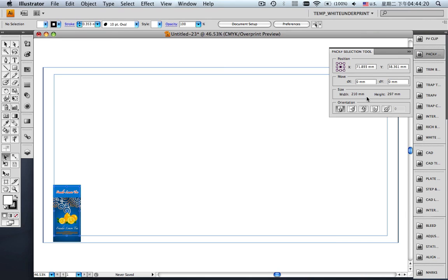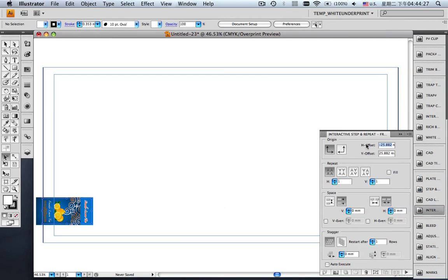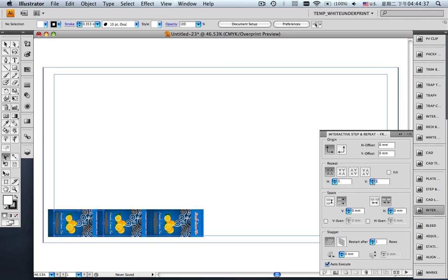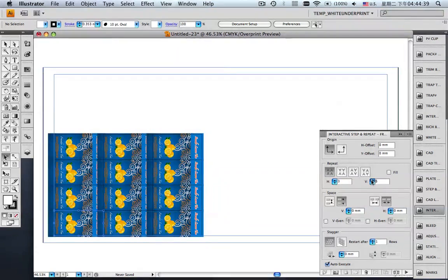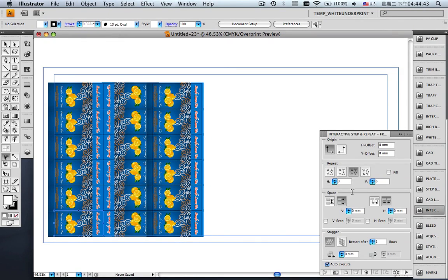Then we can add the second station. By using the anchor tool, we can adjust the relative position of two stations easily. And then we do the bleed and overlap. And then we choose the adjust overlap to modify the overlap positions between the two boxes. Then we add marks and save the file.